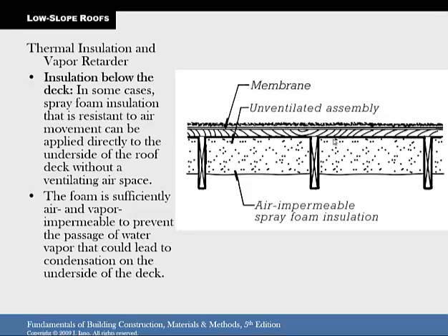Here's another detail with the spray foam insulation. We saw that on the field trip, right? They were going to do spray. They hadn't done it yet, but that's the spray-in. That's the goopy stuff that expands and fills in all the voids. So it's air impermeable, which means you don't have to have the air gap because it supposedly is sealed. Of course, my fear with that is that there's always a little hole somewhere. But if they do it right, as with everything, it should cause you no problems.